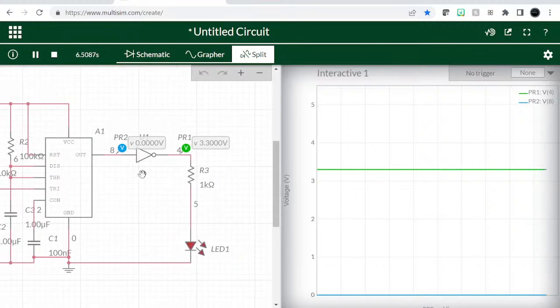But the system still assumes that if the input is low, then the output is high. So the input, which is the blue line, is off and the output is high, and that's probably because we didn't connect this with a power, so it's assuming it has power. Yeah, that's the problem. There's an assumption that the inverter is powered separately. Not the case in this circuit, but it's making that assumption. And that's why when the input is 0 volts, the output is 3.3 volts, which is the maximum output from that inverter. So I can understand that, but let's power our circuit one more time.